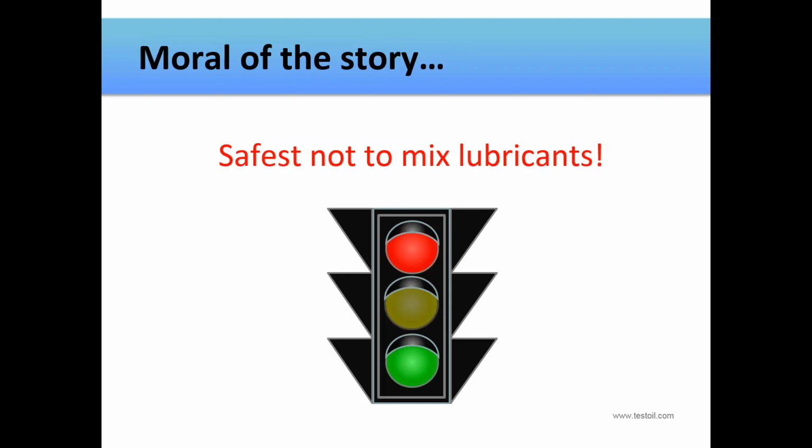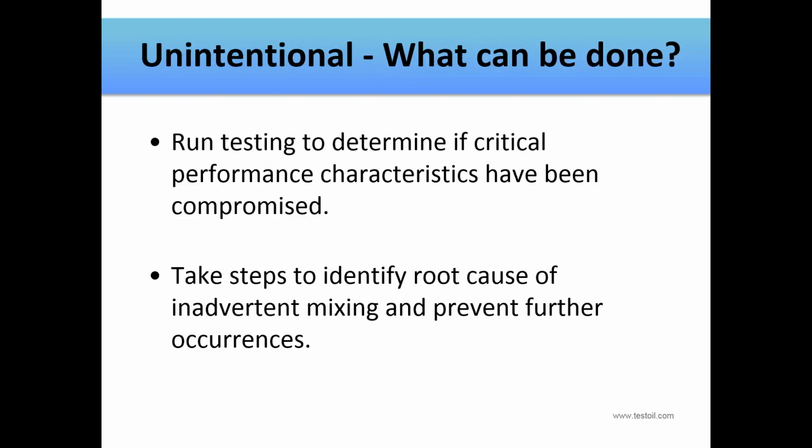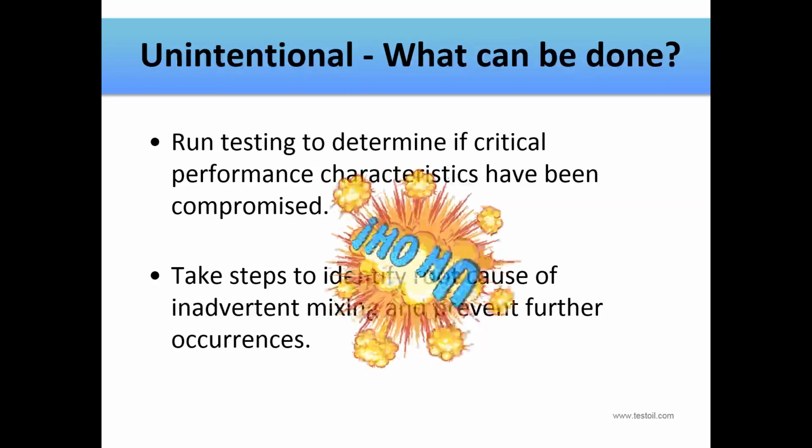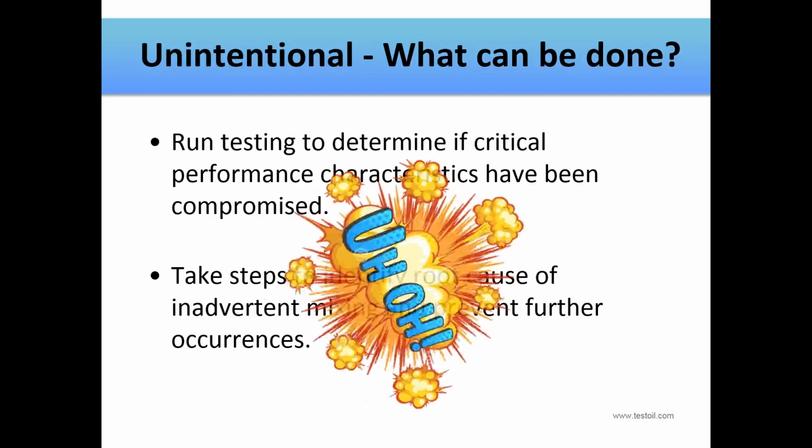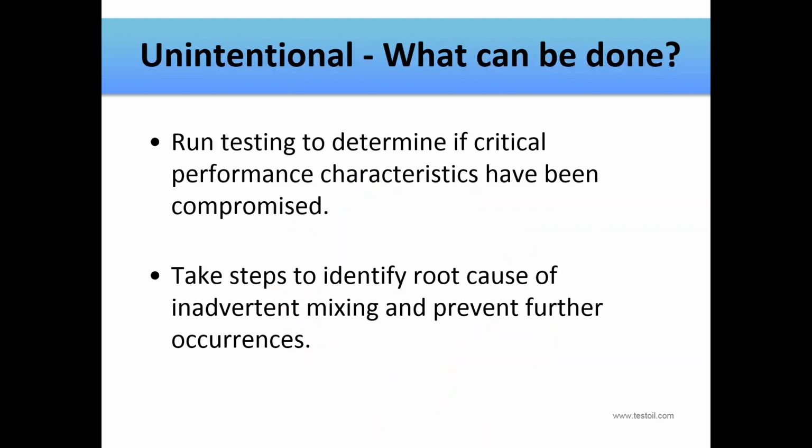So given the issues that can occur, it's obviously safest not to mix the lubricants, but in the real world we know that mixing happens for one reason or another, and we really just need to know how to handle that. So if we have unintentional mixing, there are steps that can be taken to aid the determination of possible issues as well as the severity and implications of those issues from the mixture. The lubricant can, first of all, be tested to determine if the critical performance characteristics have been compromised.